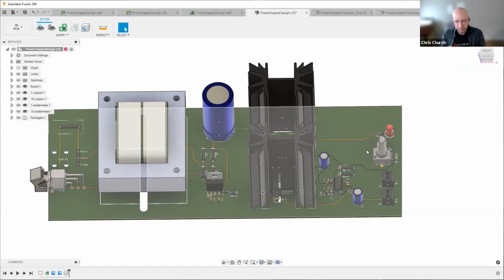When we're doing that, the challenge always becomes how we actually repeatedly do those bends and do that height placement, et cetera. So just like we would do a shim with that transformer, if we had needed to, we can do the same thing with the LED, and you can even model that up. One of the very common things out there is to use standoffs with the LEDs. There are a lot of them available if you need to set it at a certain height. You can bring in that model, add it to your EBOM, and then we can see it already as part of it. When you upload that ODB++ file out of Eagle to us, it'll automatically bring that in.